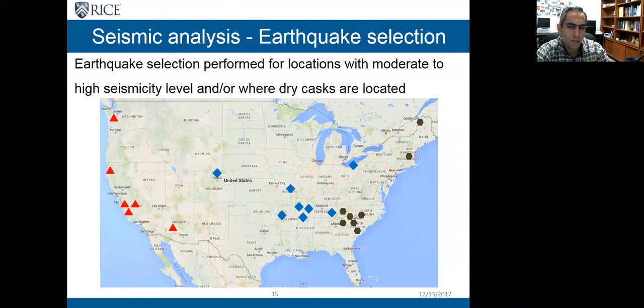The way these casks have been constructed is that they're not attached to the foundation. And the concern about the seismic motions has come up recently. And as I know, it's not allowed based on the standards to attach them to the foundation now. So that has been the traditional way, the conventional way these casks have been constructed.